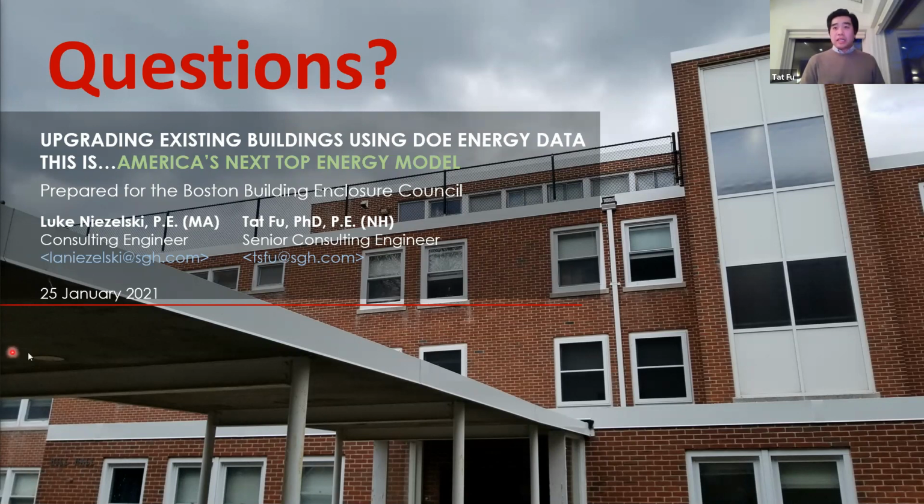A second comment I see from Greta is that energy savings is an important goal, but not the only goal, and about a comfortable environment. I completely agree, and that's the reason why the university, for the case study, wanted to go with low E coating, even though it will increase the heating consumption, and they only have heating for that particular building. They worry about comfort in the summertime for the students that may be living there.